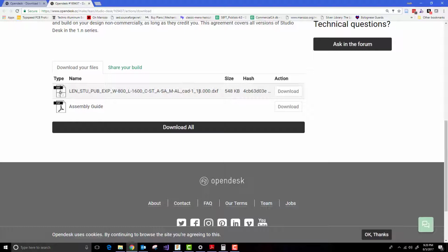the multiple sheets if you have multiple sheets of plywood. And the 18.00 is the thickness of plywood that they have designed this file for. So this particular file is designed for 18 millimeter plywood. When I did the desk, it was designed for 18 millimeter plywood. I used 18.2 millimeter plywood, and I just had to hit things with the hammer a little harder to get